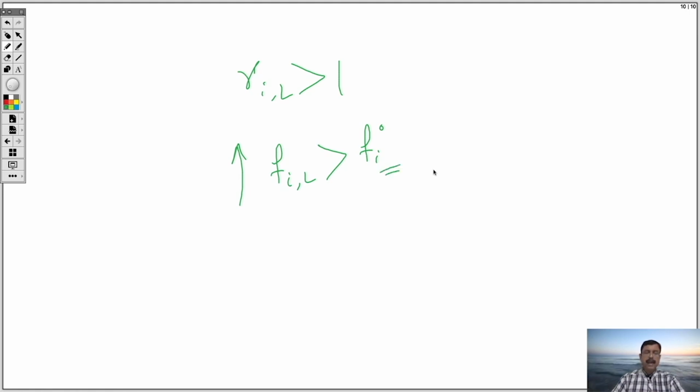And this can be attributed to the increased repulsion between the molecules in the mixture than in the pure state. Obviously, in a few cases, the activity coefficient will be lower than 1, indicating that there will be increased attraction between molecules in the solution state and it will yield less tendency to vaporize.